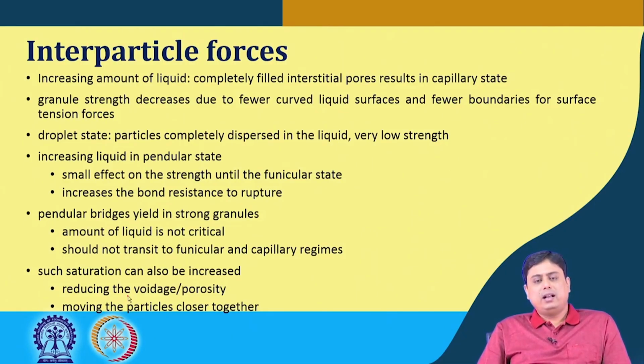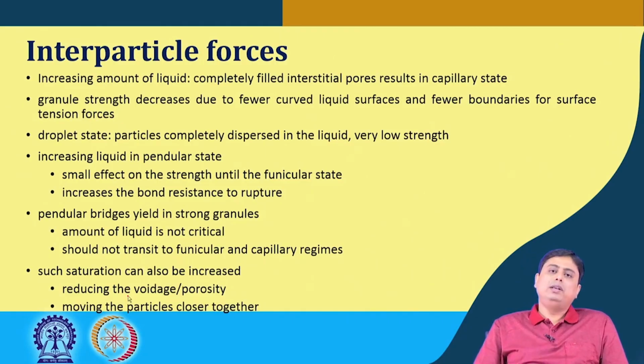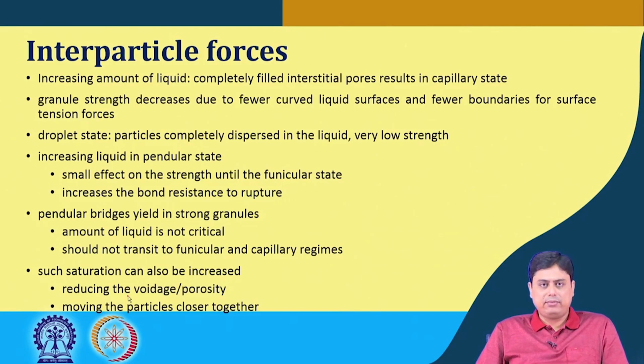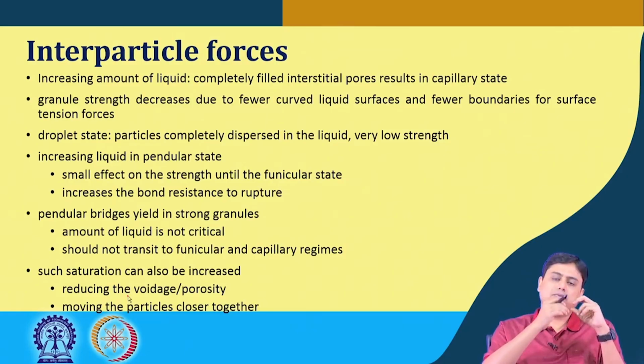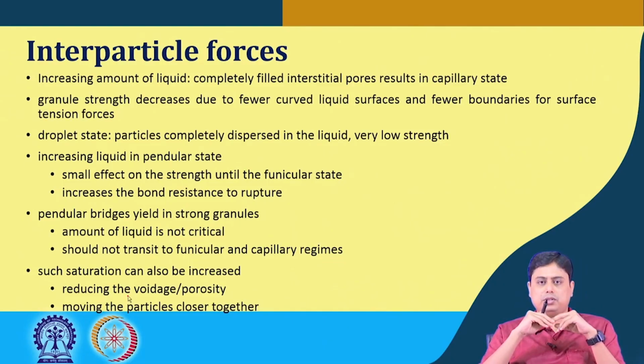So, it has been seen that an increase in the amount of liquid in the pendular state has only a small influence on the strength until it moves to the funicular state. If it is in the pendular state and you increase the amount of fluid, it increases the bond resistance to rupture.